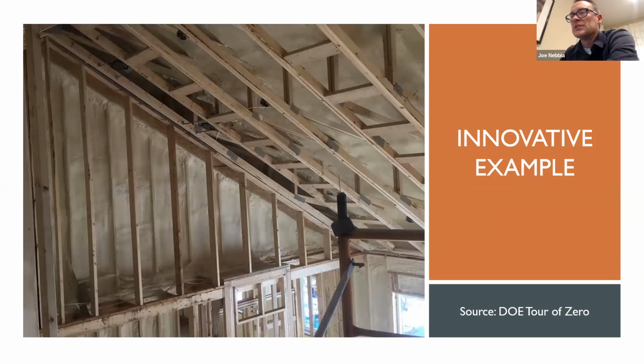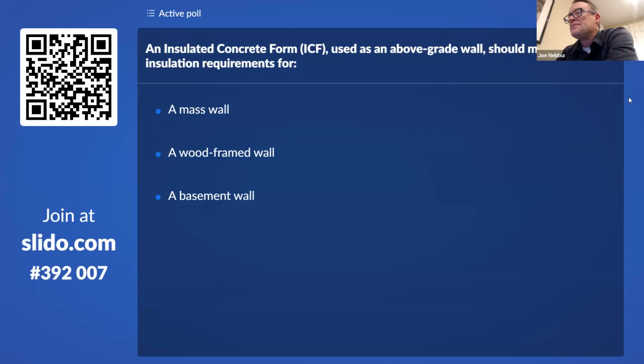More spray foam. This is closed cell, I think in Minnesota, where they've done the whole house this way. So here you could see, for the builder who asked about this, I think they're actually covering the framing there at the top. So you might get some amount of continuous insulation value and be able to claim a U value benefit to that, because it's not interrupted by framing in that case.